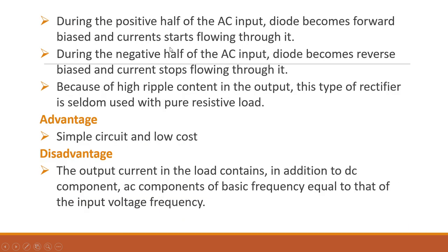The advantage of the half wave rectifier is that it is very simple and very cheap, but the problem with the half wave rectifier is that the ripple is large and the power loss is huge because only half of the signal is getting to the output.